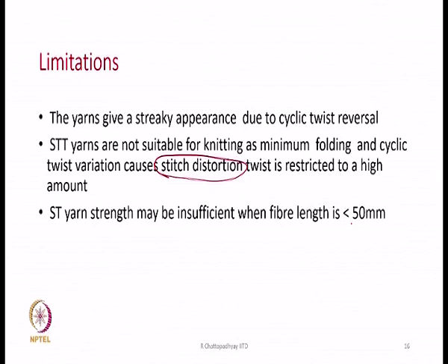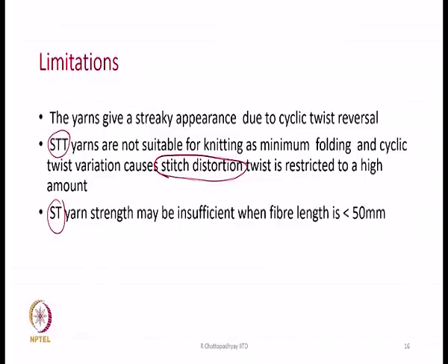ST yarn means self twist yarn, and STT means self twist yarn that we have again taken for further twisting, then we call it STT yarn. So, there is too much twist, so the yarn is going to be maybe twist lively also. And use is pullovers, carpets and any other outerwear products that we make from wool or from wool synthetic fiber blends. These are the possibilities, and with that we close this particular discussion on self twist spinning.